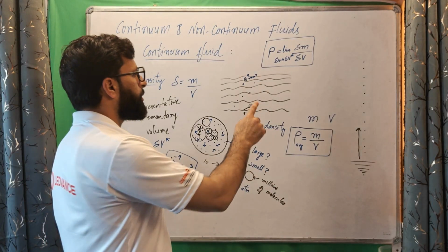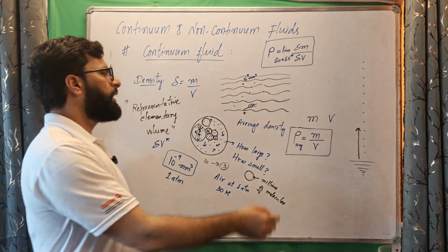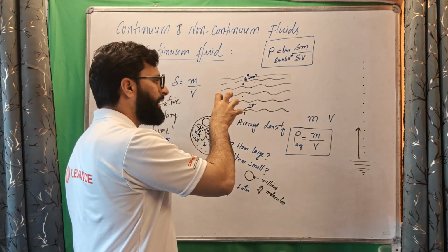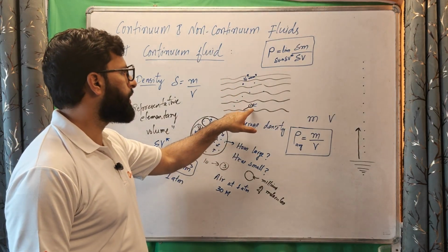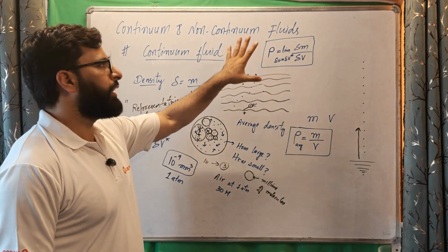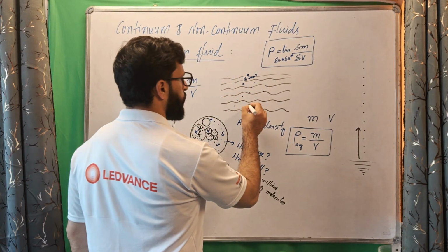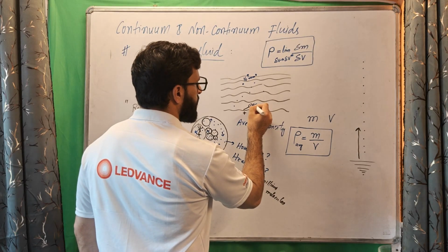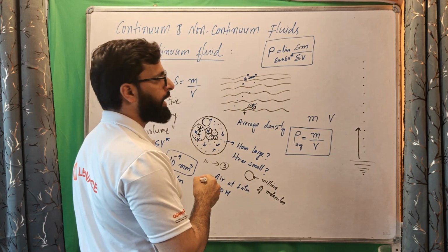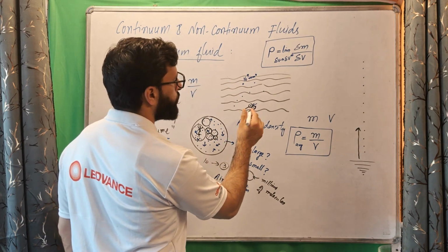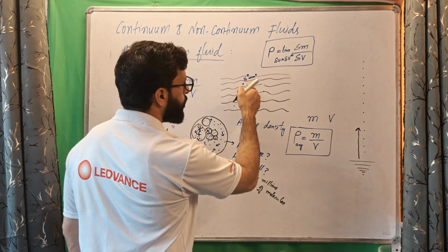So when we say density at a point is some value, we mean all of this that I have said. We mean the volume around that point contains some molecules, and the mass of those molecules divided by the volume of this small element is what we mean by the density at that point. And this way, when we move from this point to the next point, we'll still have 10 to the power minus 9 millimeter cube volume around that. So we're continuously moving from this to this. If we change the point, take a point here, we mean this volume around that point.